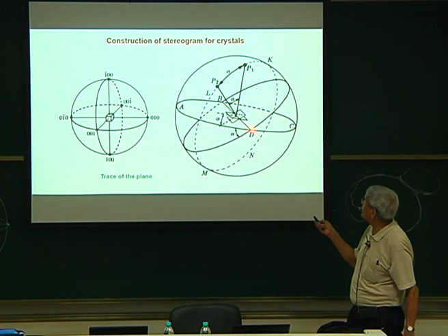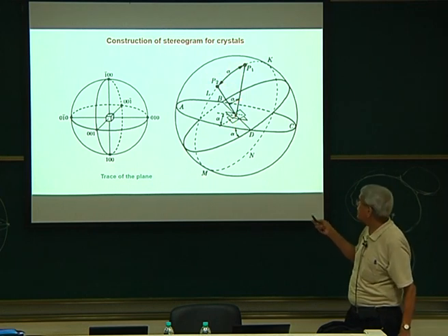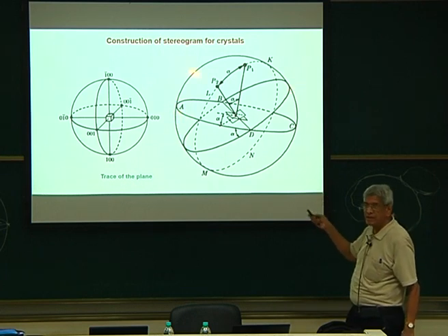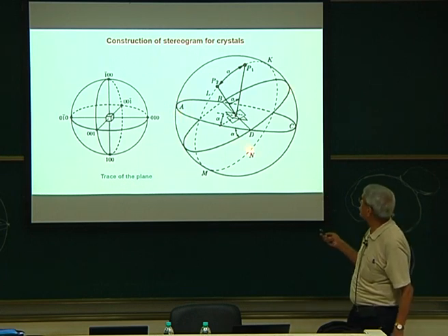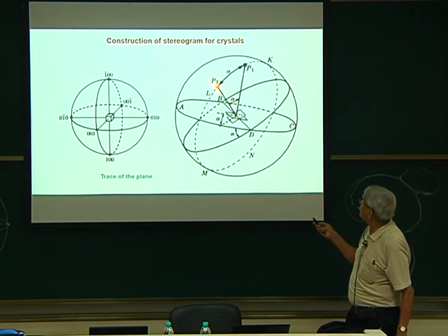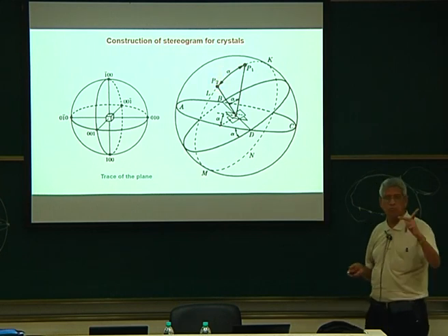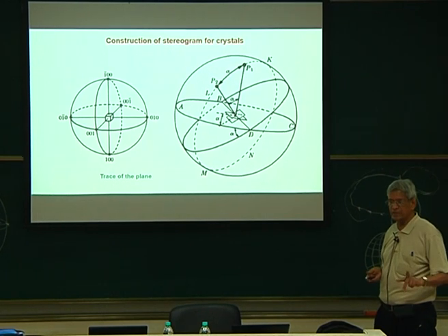If we consider 2 planes, the 2 plane normals are going to come here. But if you extend these planes, they will be cutting the surface of the sphere like this, correct. And when we want to measure the angle between these plane normals, this is essentially measuring a distance from here to here on the surface where the poles are getting projected.